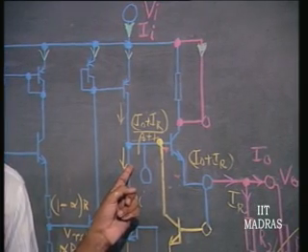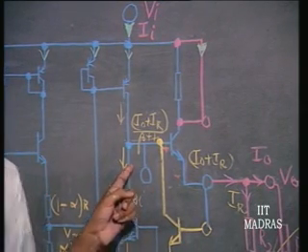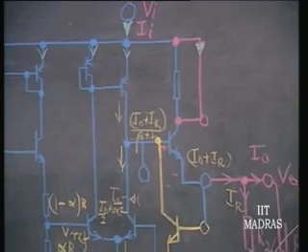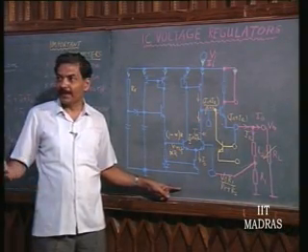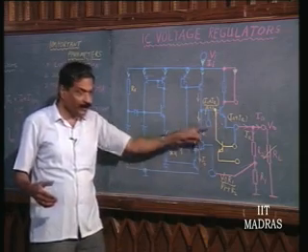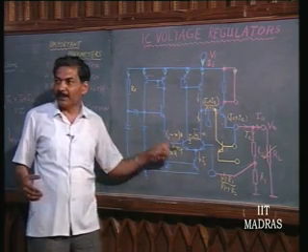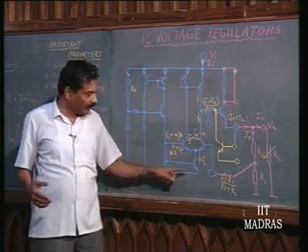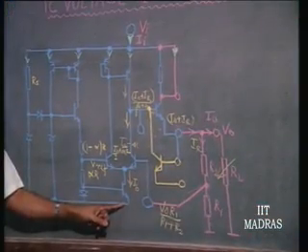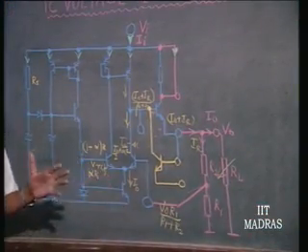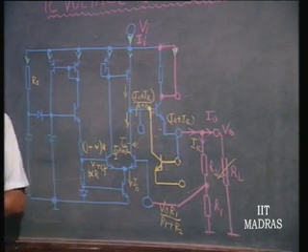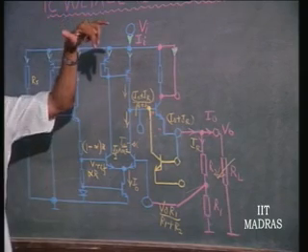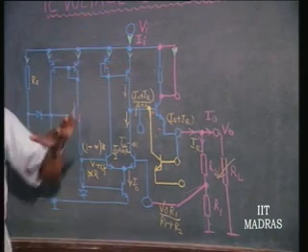Now that is as far as that output transistor is concerned, but other transistors might be having more problem than this in terms of breakdown voltage. You have to see all the transistors and see what the collector to base voltage of all these transistors is. The lowermost transistor is the one likely to carry the highest voltage in a given situation if it is connected to the input. If it is not connected to the input, you do not have to bother.